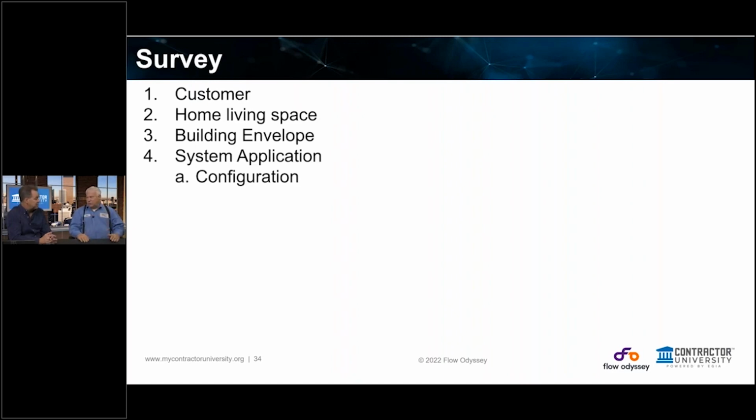What would be the evidence that someone would see that's evidence of ice damming? What would they see outside? You actually can see shingles that come up, and on the inside you actually see water spots. So you're basically seeing damage because of the ice damming. And what would be the solution for that?